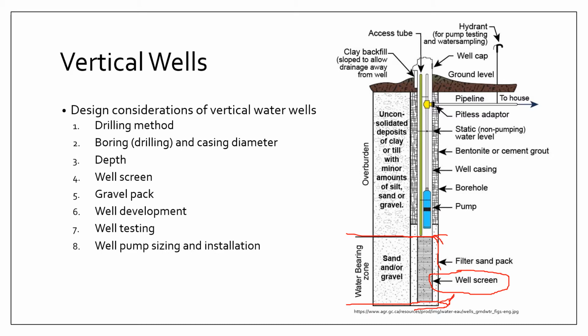The well screen has important functions, like preventing your aquifer formation from collapsing, as well as ensuring that the entrance of water in your well proceeds at the most efficient conditions, which we will be discussing later on.